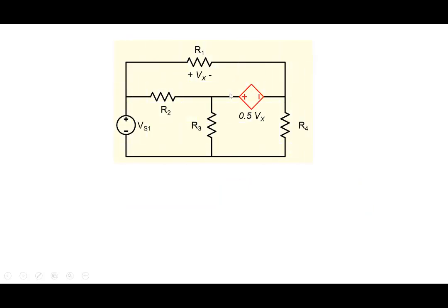Well, let's look at a case where we have a dependent voltage source, and the dependent voltage source will make it floating, again by identifying these nodes and taking one as ground. So this dependent voltage source becomes floating. When we have a floating node, we use the concept of a super node. So we combine them together into a super node, and then we write down the equation at the super node.